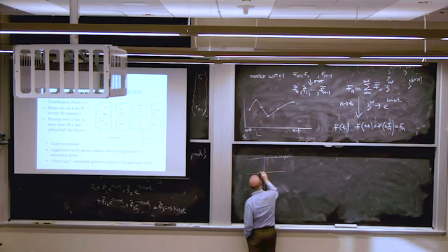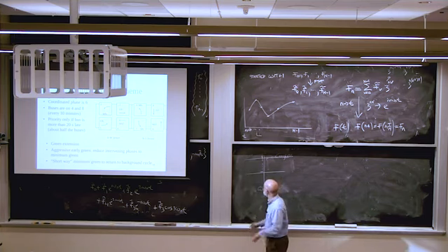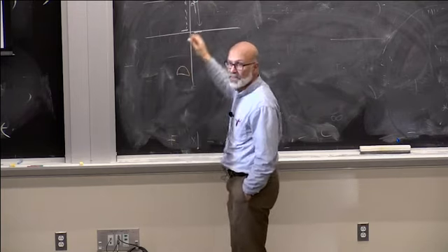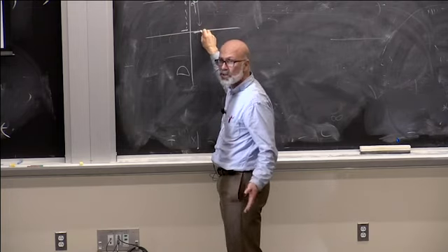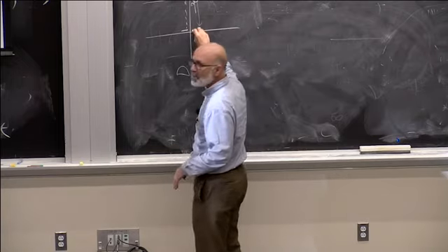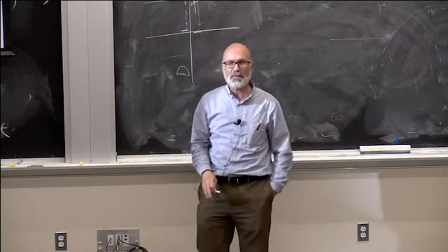Traffic comes to here, oh, the light is red, and our queue spills back, and it hurts the capacity. And the second one is starvation. The light turns green here for northbound traffic, but the light is still red here. So cars start to go, but nobody can go because they're stuck. It's starved. So they don't want to close D Street while either of those things can happen.